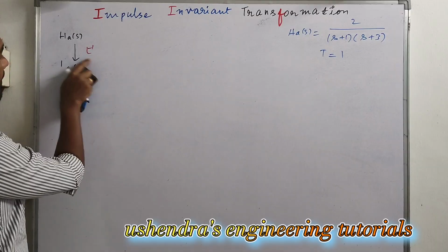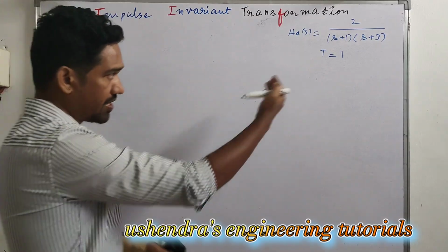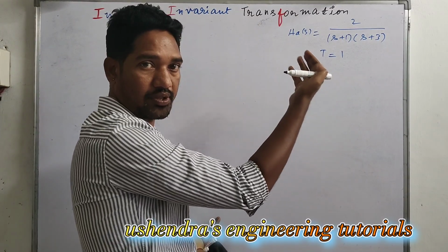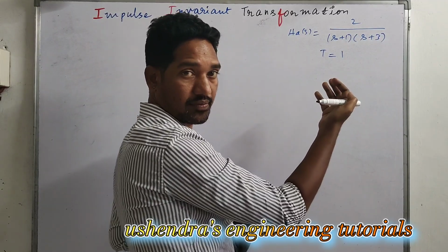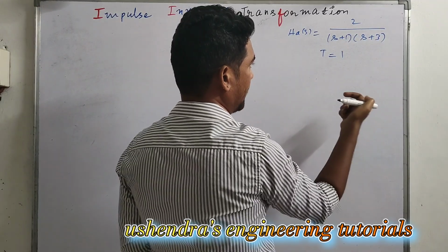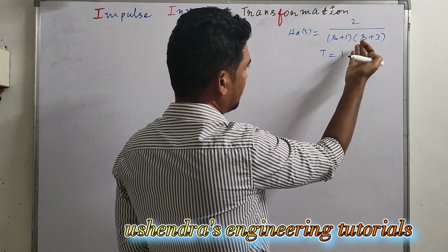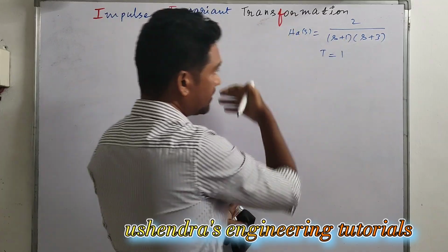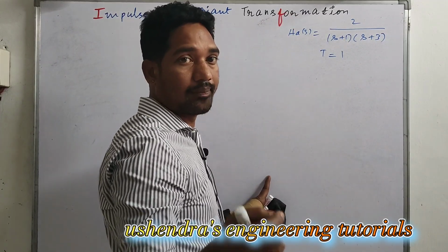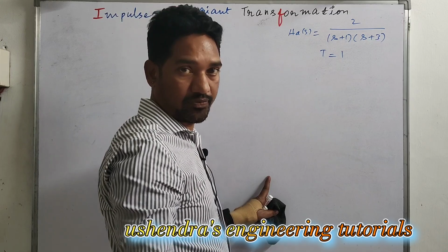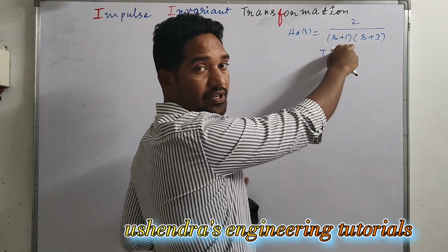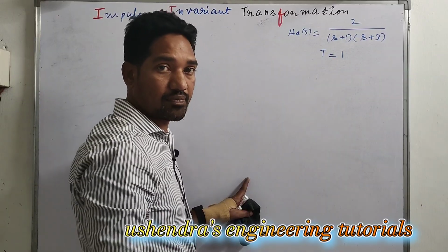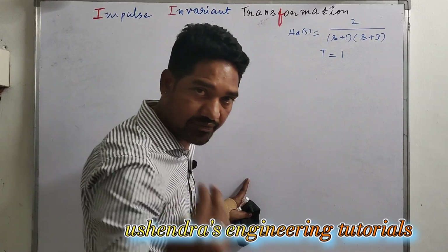And to obtain the inverse Laplace transform, if we are dealing with this numerical, we have to split that into partial fractions. During this transformation we need to speak about the pole locations and number of poles. Here we have two factors. The denominator of the transfer function gives us the characteristic equation, which gives us the information of the poles.